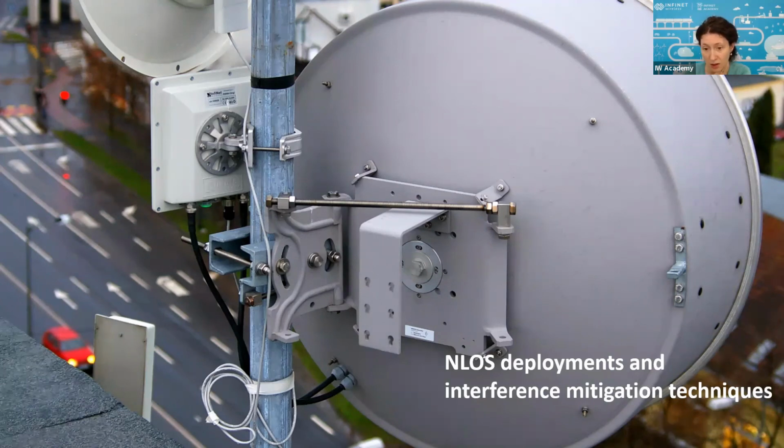Okay, in the chat section, if external antennas are used with SMA connectors, how many percent losses should you consider? Generally, it's not related. The packet loss is not related to this type of connection. Just bear in mind that if you use attenuators, for example, you should consider 1-2 dB losses on the attenuators. Okay, so 1-2 dB losses if you are using additional attenuators, but just using simple SMA connectors will not bring you packet losses just because you do this.